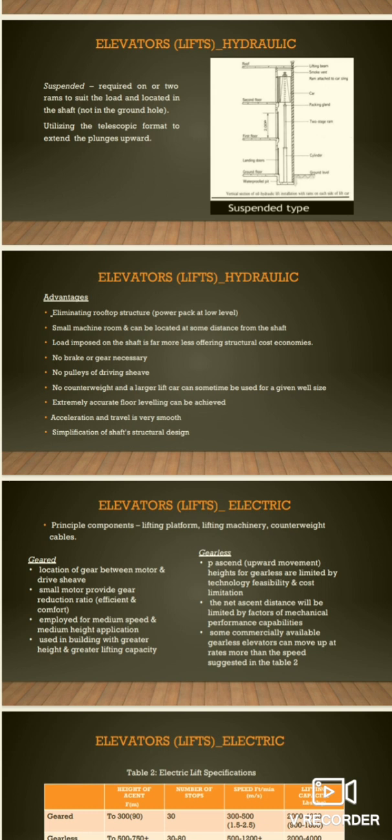And the elevator's hydraulic advantages: eliminating rooftop structure, power pack at low level, small machine rooms and can be located at some distance from the shaft. Load imposed on the shaft is far less, offering structure cost economies. No brake or gears necessary, no pulleys or driving sheaves, no counterweight, and a large lift car can sometimes be used for a given wall size.